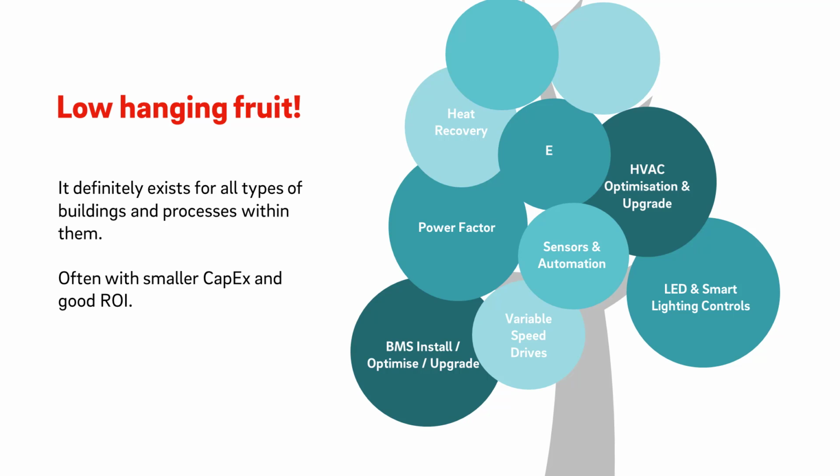An example for a commercial building is the installation of new CO2 sensors to give additional control to the building, ensuring that systems operate when they're required. But they can also be used to enhance where you've maybe previously installed variable speed drives at a fixed speed or only on-off control.